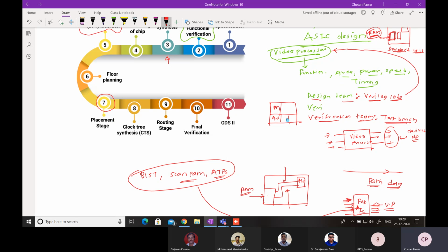While doing the placement, there are placement algorithms, block placement algorithms. What is meant by that? They find the optimum position for a particular block. For example, at this point for RAM I am getting less delay or less clock skew. Depending on the clock generator or whatever sources are available, like VDD, ground, and external supplies, these blocks get placed.